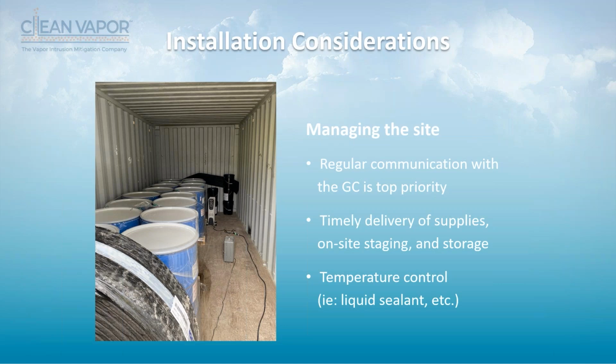If it's going to be cold, you're going to want to have some place where you can put spray applied material to keep it above 40 degrees. Also, it doesn't hurt to keep this stuff boxed up because you don't know how secure the site is. But all these things, you want to have these conversations up front, so when you get on site, you are snapping along and you're not holding that GC up one bit.